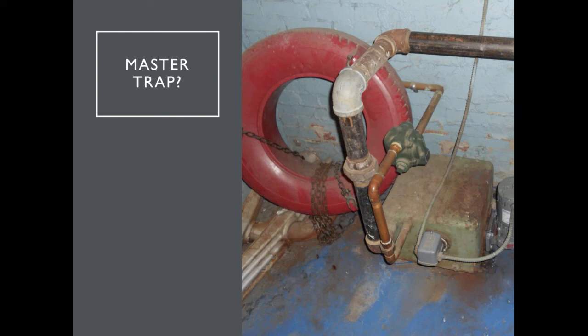If it's over 2 psi and it's for space heating, I would look at lowering it down. If you work on boilers for brewers, they try to operate at 12.5 to 13 psi, which is really scary. It's way up there, and you're going to have a lot of issues with it.